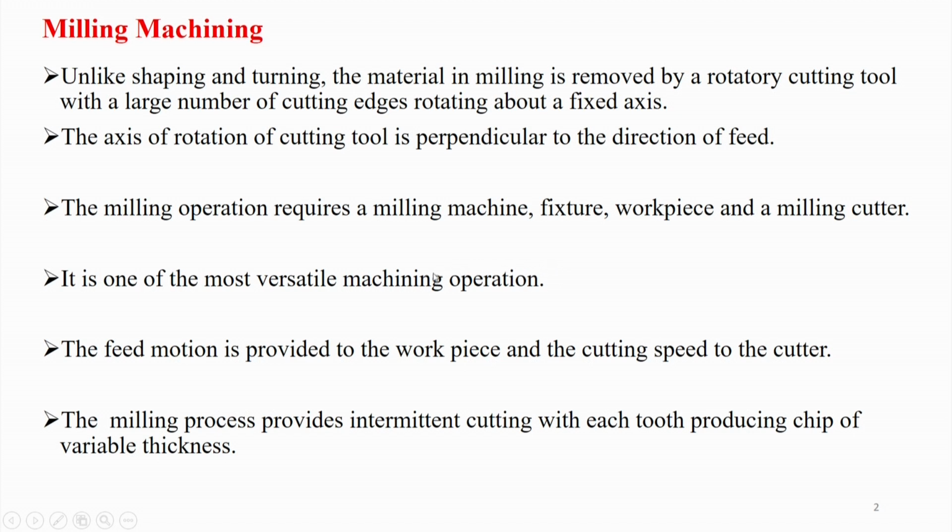It is one of the most versatile machining operations for producing flat surfaces and curved surfaces. Mostly we can machine rectangular jobs also. The feed motion is provided to the workpiece and the cutting speed is provided to the cutter. In the turning operation, the workpiece rotates, but here the workpiece is stationary relative to the rotating cutter.